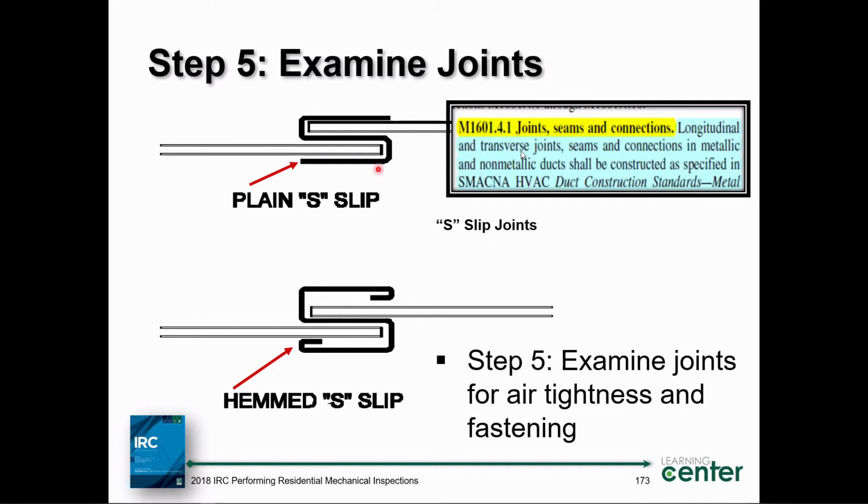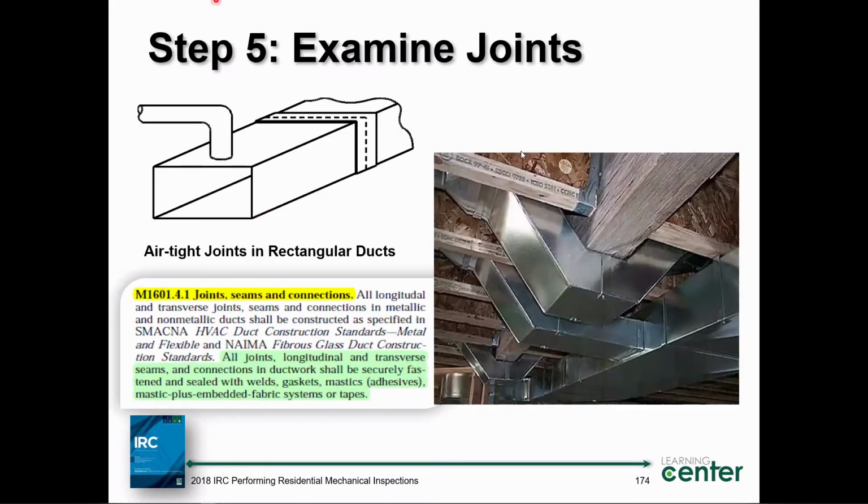Tells you how to put the ducts together using slip joints, whether they're hemmed or unhemmed. Slips, drives, kind of like this here. Your slips go on the top here. Your drives get beat on the sides like this. See, this is a drive. You actually squeeze the ducts together by hammering the drives on the sides accordingly. Isn't this beautiful? Look at that.